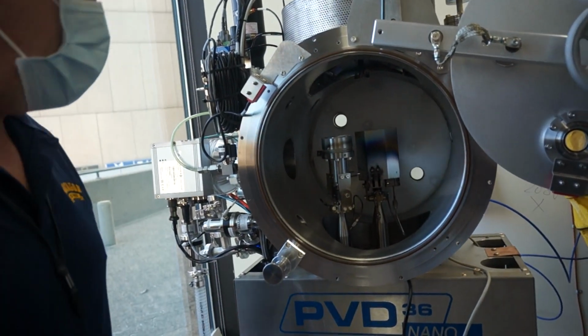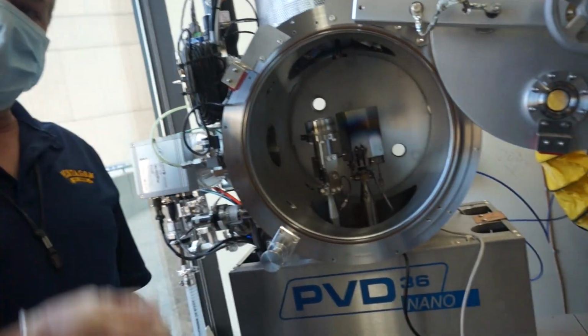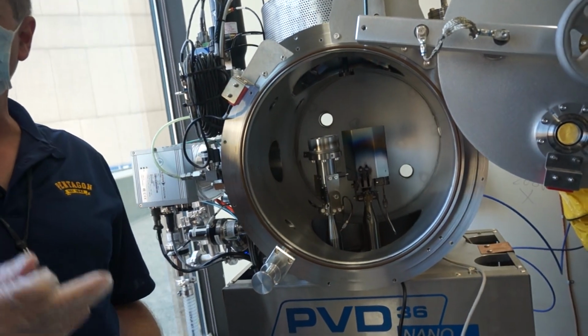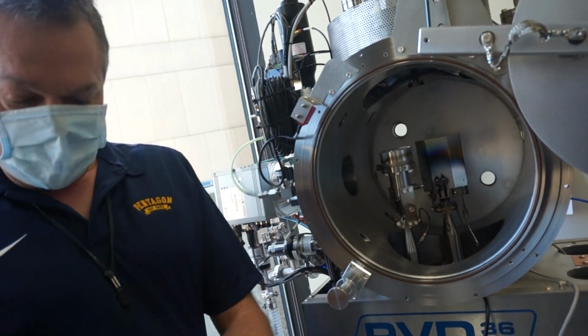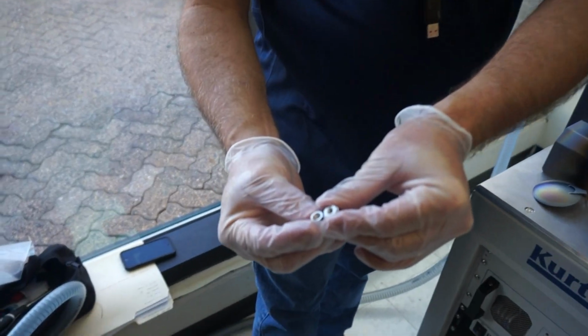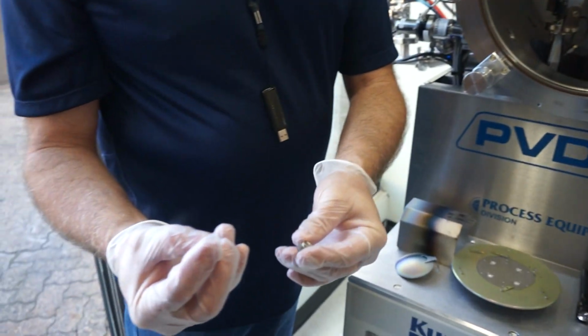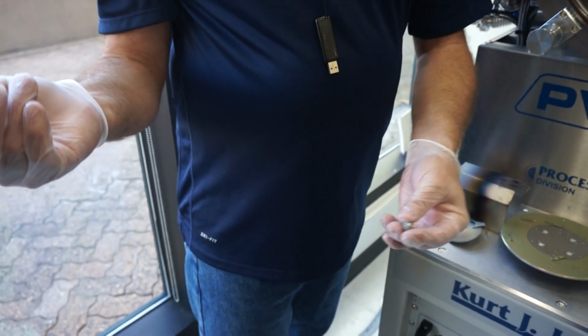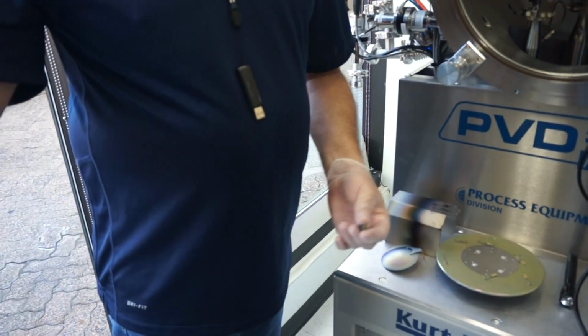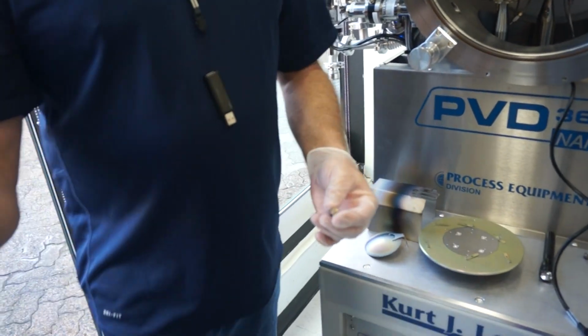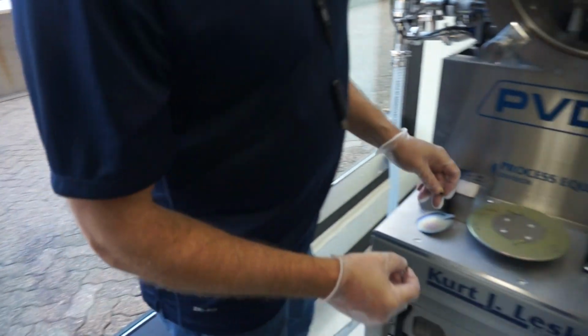So you either have vented hardware, where you put a score along the side of the threads to give it a path to escape. You look at these two: one has a cavity, the other doesn't. Lesker doesn't manufacture this; we buy it by the gazillions from somebody. If they change, then I put this on not with this portion facing the trapped volume. I just spun it around. I just wanted to point that out.